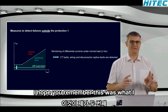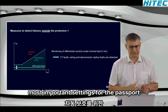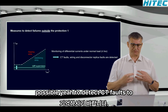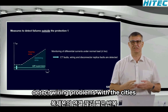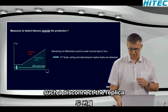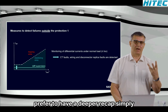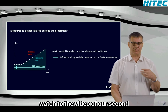I hope you remember this was what I explained in the second tutorial, the most important settings for the busbar differential protection. And with these settings, it will be possible to detect CT faults, to detect wiring problems with the CTs, and you can also detect problems in the disconnector replica. Just a short repetition. If you want to have a deeper recap, simply watch the video of our second tutorial.